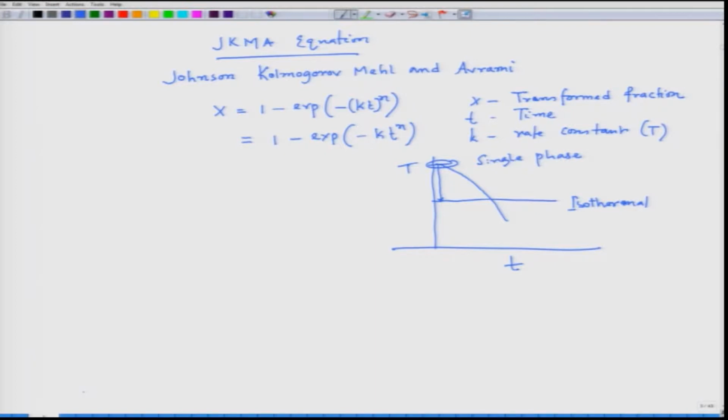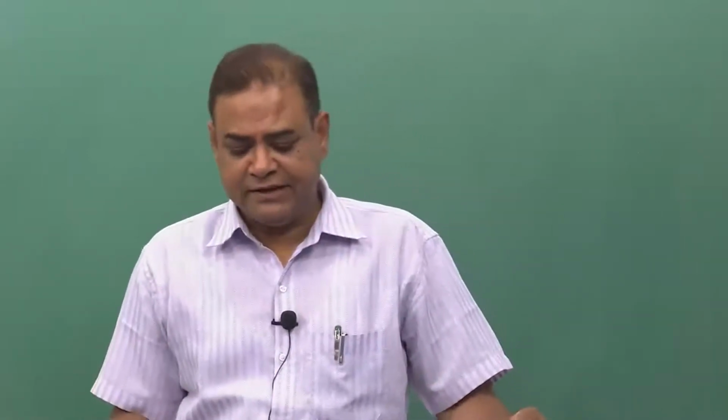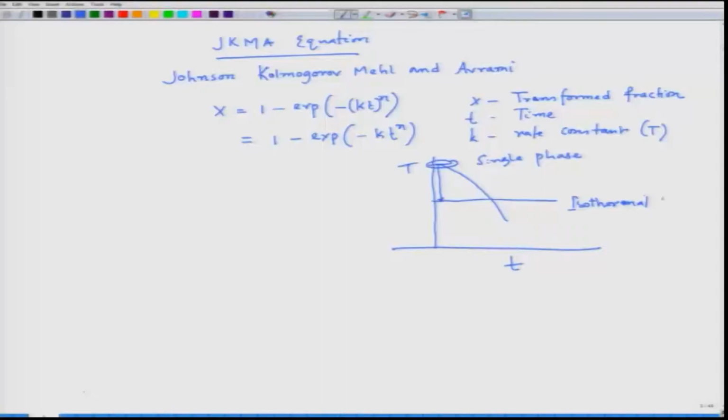In case of solidification, everything should be liquid, and in case of solid transformation, we should reach a point where it leaves us single phase. For example, in case of phase transformation in steel, we generally take it to austenitizing temperature, where everything transforms into austenite, and then we start transforming. Either we can go through this route or we can go through this route. So, this is basically nothing but continuous cooling. We have explained this part also in our phase 1 lectures. And now one can plot x as a function of time at a particular temperature if we carry out the experiment in isothermal mode.